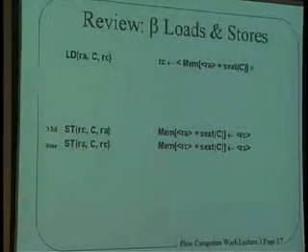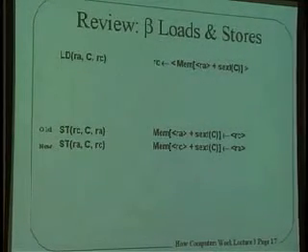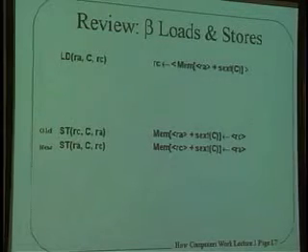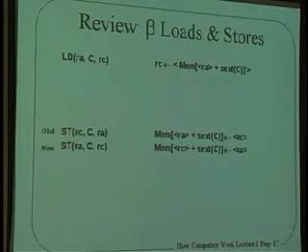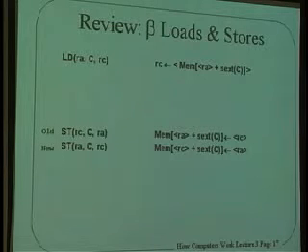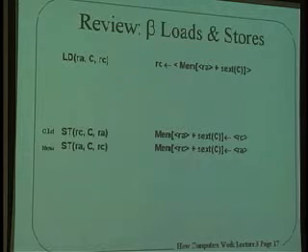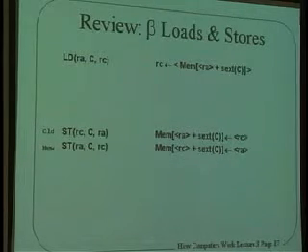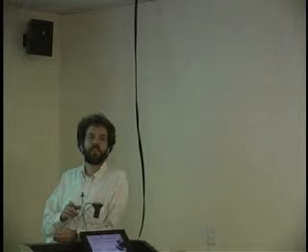Loads and stores. This is a way of moving things from the memory system into the register file and vice versa. Remember, load takes the contents of RA plus C, uses that as a pointer into the memory file, and puts the result into RC. Stores actually work in one of two ways, and I noticed, unfortunately, yesterday, you guys printed out a reference thing for the beta, not from the last term that I taught it, but from the term before. And we actually changed some stuff. So one of the other things I'm going to do when this class is done is ensure that we get the right stuff out to you guys.